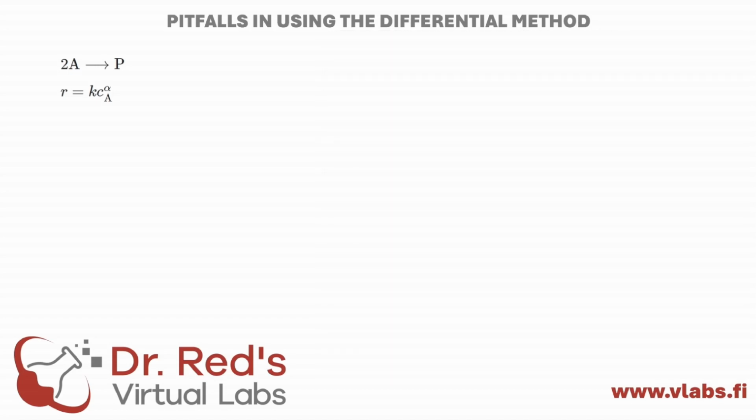Because we used a batch reactor, the rate of change in the molar amount of reactant A is the product of the reaction rate and the reactor's volume. If we assume constant density, dividing by the volume yields the derivative of concentration. When we plug the rate equation into the mass balance, we get a differential equation with concentration as the independent variable. Theoretically, this equation could be integrated to find the concentration of A at any time, except that we don't know the values of the parameters.